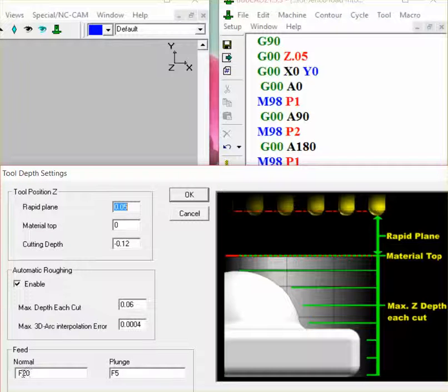You have to have the F in front of that feed rate or you will get all kinds of terrible programming errors and you won't see it, but it's got to have the F's in front. It's an absolute have to. Alright, we have that set.